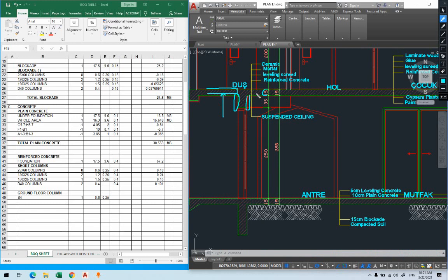For example, this extra from this side is different, because if this side is 15 and the other side is 12, then the beam height from this side is different than from this side. And if I use both sides, I'm supposed to get the same height of the column, because the column basically ends at the bottom of the beam. So for me, which one is easier? The top part is easier. That's why we go to the top and we take out the height of the beam from it.